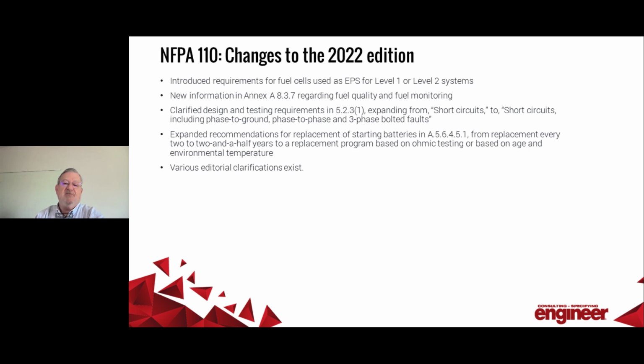There are also expanded requirements for short circuit and design testing. The previous edition said only that generators would be tested for short circuits. 2022 adds phase to ground, phase to phase, and three-phase bolted faults. This requirement may wind up being more interesting to manufacturers than it is to facility designers.